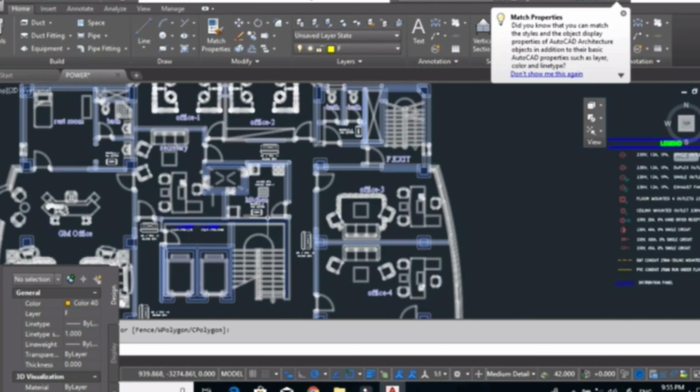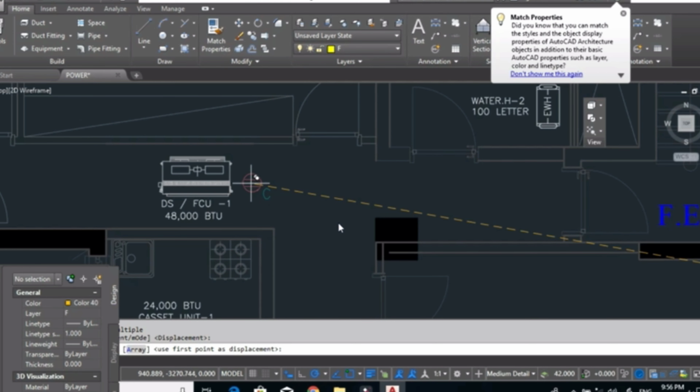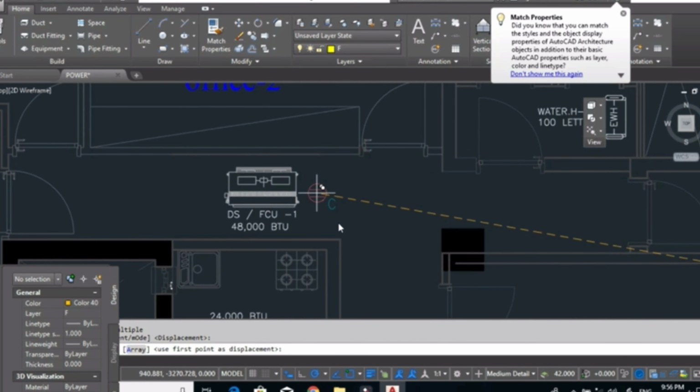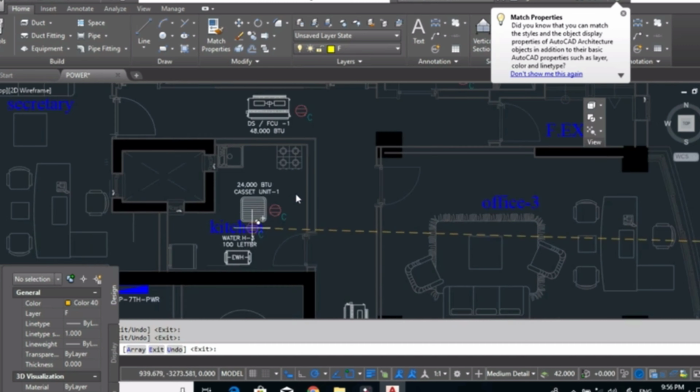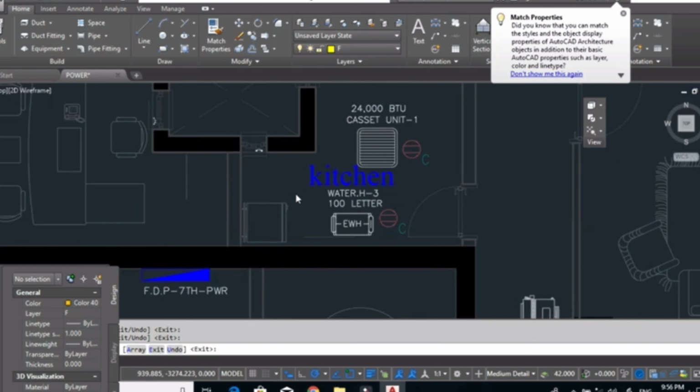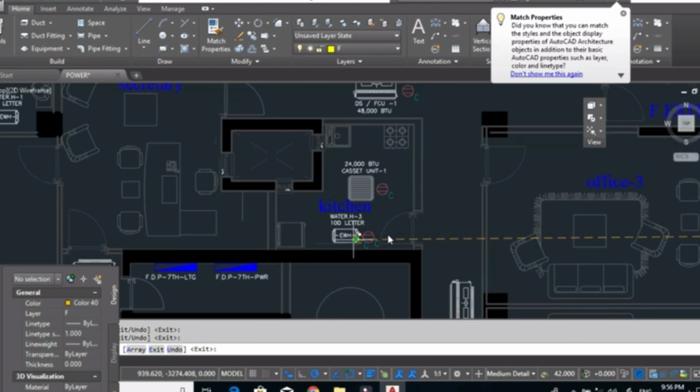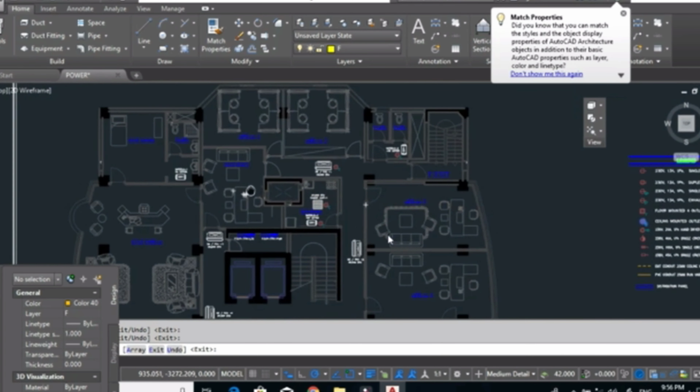Now I will start to distribute this outlet near the equipment. Copy, ceiling mounted outlet, also above the false ceiling. I know that all this equipment has an access door for maintenance. Here, one, and again here I will put one also, and here for this cassette, and also here this water heater is horizontal type above the false ceiling.